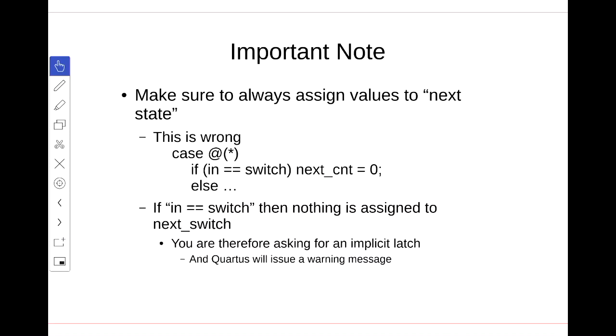So if you ever have an if statement in there, be very careful, because if statements might mean that you forget to assign something to the different outputs. And in combinational logic, that output has to exist no matter what. So make sure you assign it there. I'm going a bit quickly because I'm assuming this is revision, but feel free to raise your hand to stop me at any time.